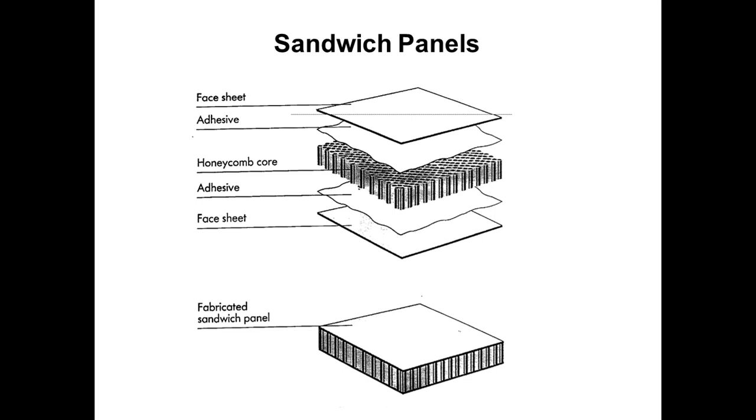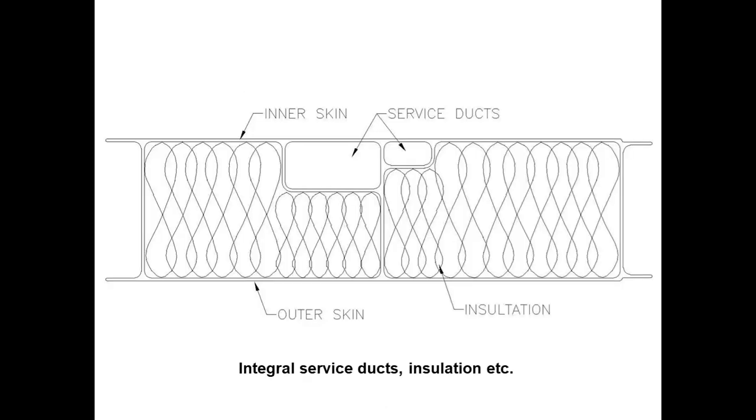What you're looking at here is say a honeycomb aluminium core. It might be foam, it might be laser cut foam, or CNC cut foam, which we'll look at a little bit later on, where you can get more complex shapes. But if you're making a simple flat panel, something like an aluminium honeycomb core will be very, very good. And of course, these cores can be as deep as 20-30 mil, so you can end up getting a floor section out of a composite FRP and aluminium honeycomb core panel.